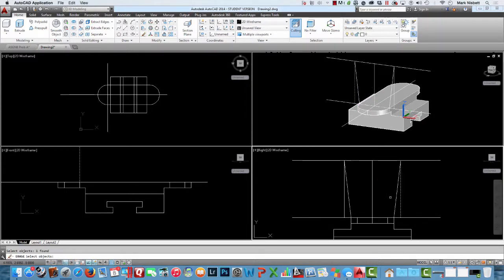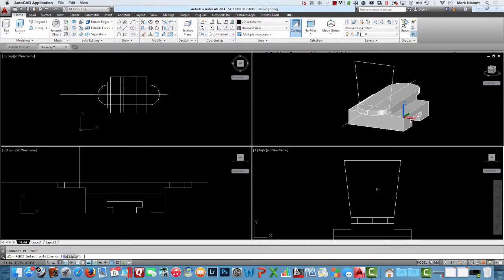We can see it. I can erase these. Okay, trim this stuff up. So we're going to trim this stuff here, like so, and erase this middle one. And I'm going to use PEDIT to edit this polyline here. We're going to turn it into one, say J for join. Pick those two. Okay, so now we have a polyline that is these three lines.